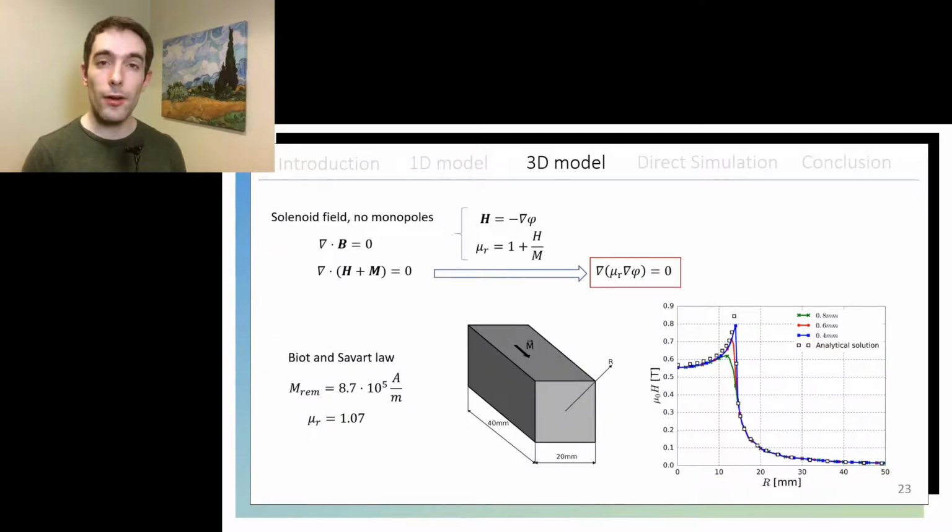Finally, I had to prove the correct resolution of the magnetic field, and since there are no electrical fields involved in this problem, it is only necessary to solve the continuity of the magnetic flux. And at the same time, since there are no electrical fields, we can express the magnetic field intensity by a gradient of a magnetic scalar potential, and that would lead us to that Laplacian equation you see there in the red square that is multiplied by the magnetic relative permeability of the medium.